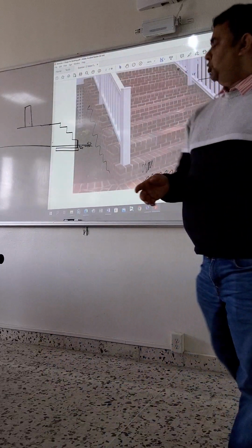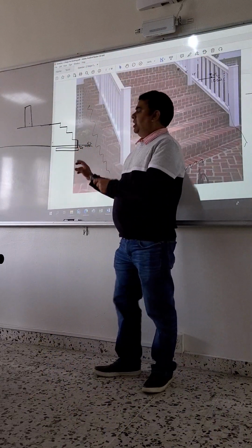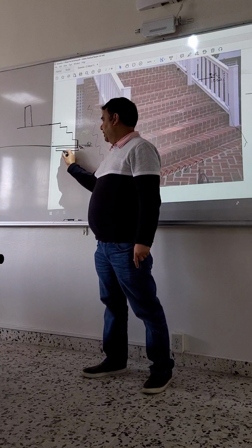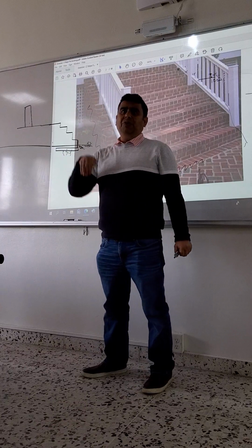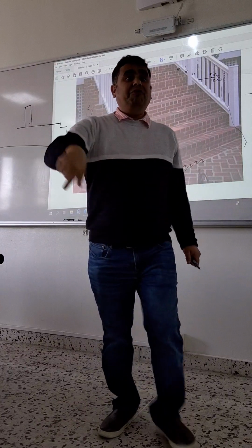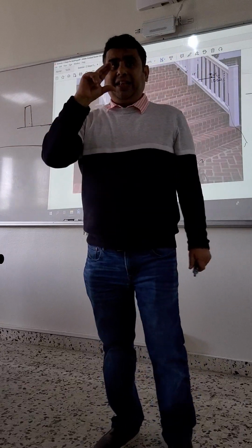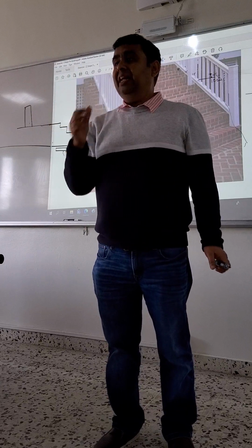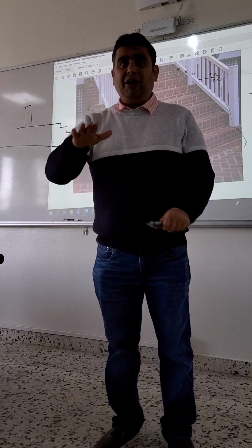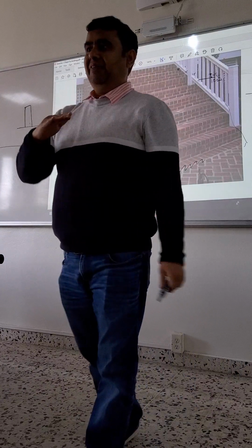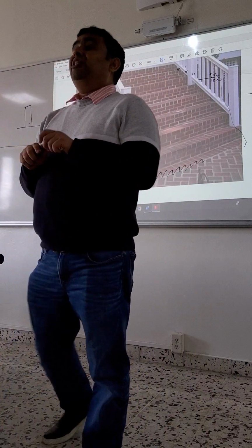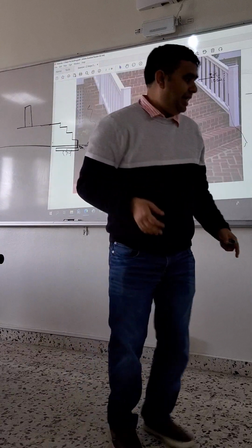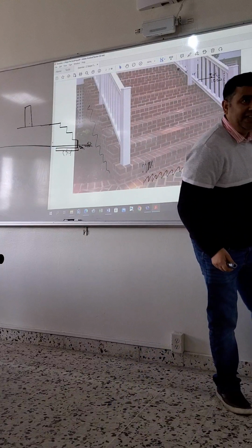Sometimes we do the plastering here also. Why? Because if you are not doing the plastering here, water, so this means the soil, here there is concrete. So the concrete soil will not go inside. That is why for making the wall, they put the concrete grade beam and then make the wall. Generally the level of the grade beam is above the soil level. So we don't want your wall to touch the soil. That is why here there is a skirting. This is sometimes known as skirting.